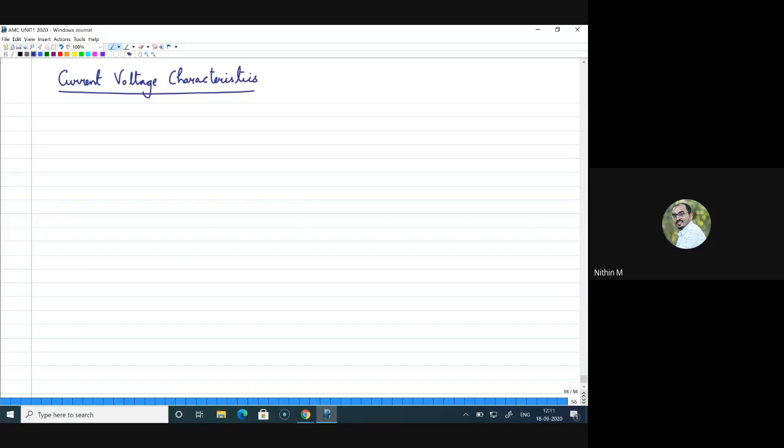Right. So far we understood that when you apply a VGS, application of this VGS will definitely induce a channel. We have to make sure that VGS is greater than VT for the channel to be present.